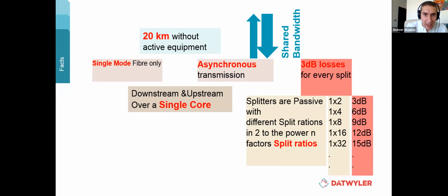And also you need a way to measure it and test your system. Where is my loss going? I know that my splitter is losing 3 dB, but where is the rest of the power going in my fiber channel? So you have to have the right equipment and procedure to test a GPON. And this Werner will talk about later today.